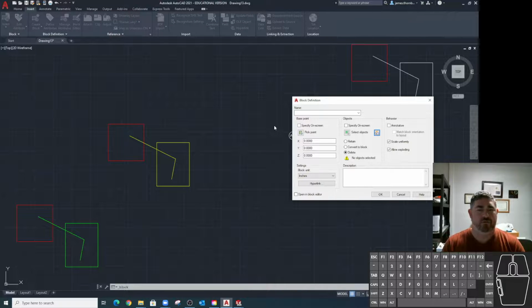And we can, of course, use some of the parametric stuff, and we'll get to that when we go into dynamic blocks. And we can have attributes, which have properties and things for them. So we'll talk all about that later, but for now, just be able to create the blocks, looking at the properties. Here under annotative is a really good one. Turn on and off the scale uniform, and those things allows you to do it.